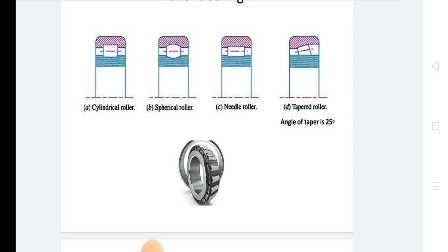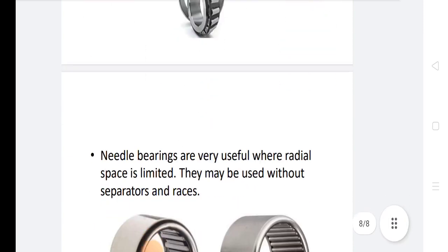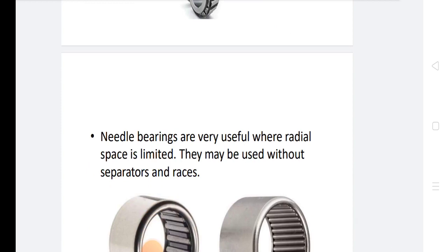Machines used 8 hours per day and not always fully utilized: 12,000 to 20,000 hours. Machines used 8 hours per day and fully utilized: 20,000 to 30,000. So it is very important for bearing life in industrial applications.